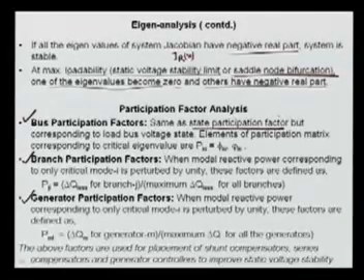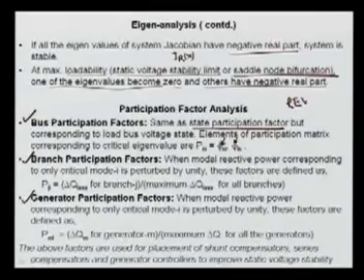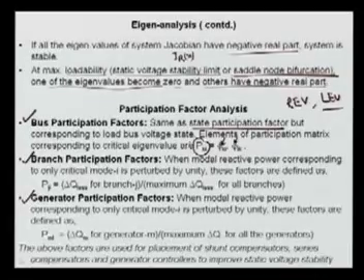It is nothing but the multiplication of the vectors obtained, that is, the right eigenvectors and the left eigenvectors, and then we can get the participation factor. But it corresponds to a load bus state. If we are taking the bus state of a load bus, then the voltage participation factor can be this.